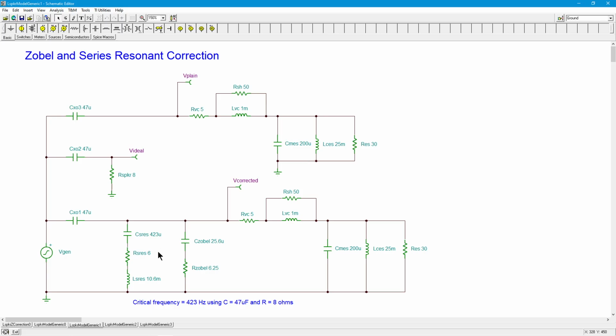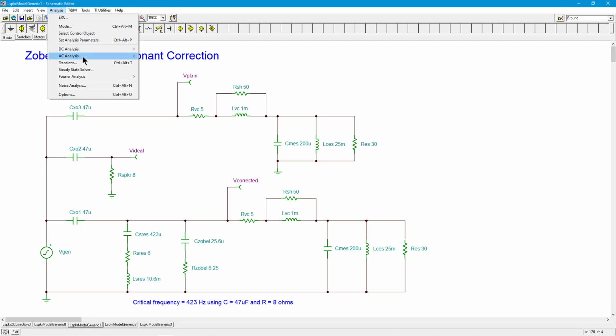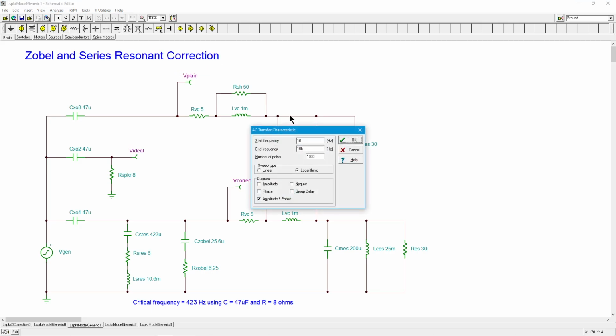And then you can control the Q of that, how tight the curve is, through the ratio of C and L. You raise one and lower the other. So you might double this, halve this. It'll give you the same frequency, but all through the Q. So that's how you can kind of play with that. But in any case, they'll go through and calculate this stuff for you. But I will tell you that there are assumptions made, and this is not necessarily perfect. So let's see what this little online calculator gives us. I'm going to do the same exact thing, do a Bode plot, see what we get.